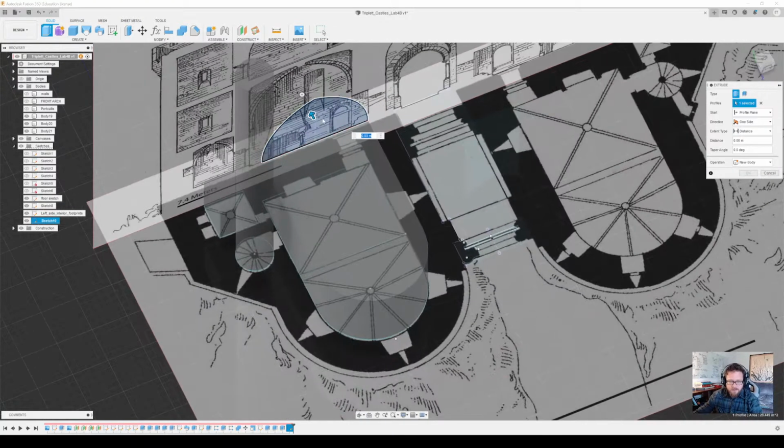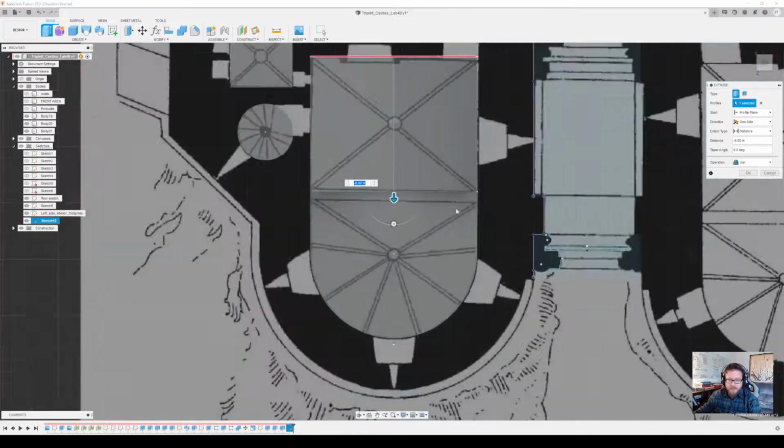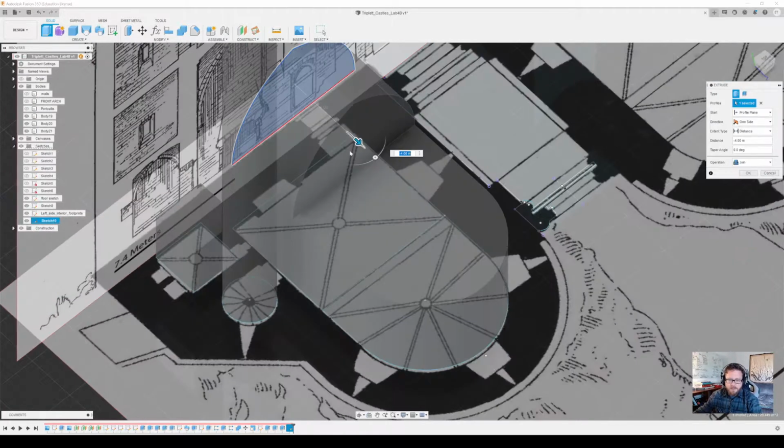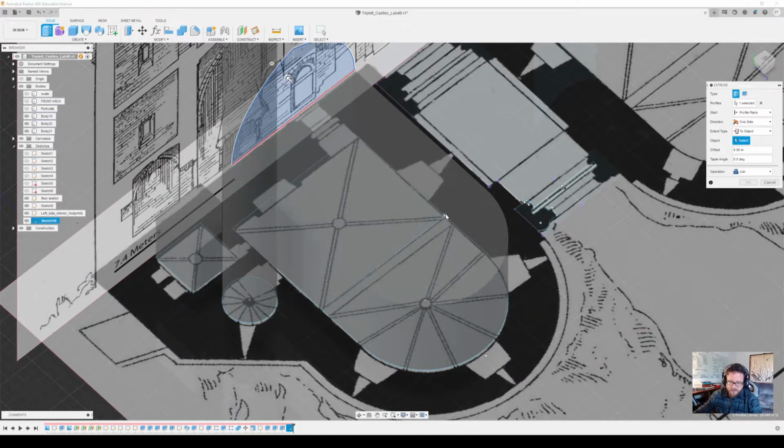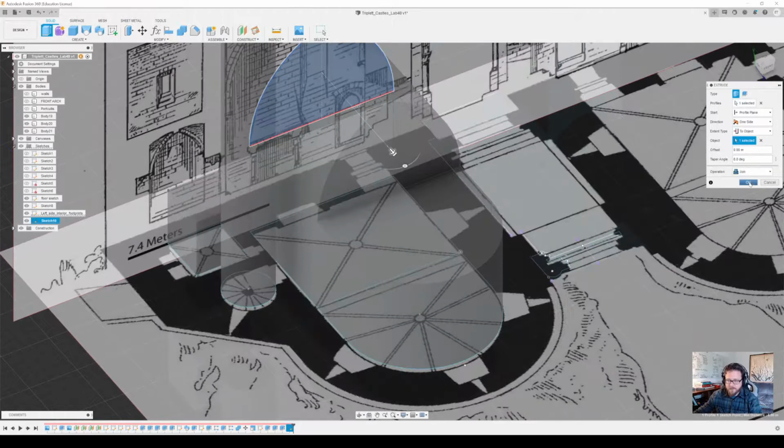Okay, so there's a couple of ways to do this. I can pull it out like this and then look at the top view, and when it lines up with this line, I can say -6, that's fine. Or alternatively, there's another option I haven't shown you all yet, which is you can do your distance right here, and it says you can measure. I apologize. We want to go to, instead of extent type, we want to go to an object. So what I'm going to do is say to object, and then say extrude it till it hits this point here, and that, if you look in the top, is what we're actually trying to snap to. So that's a useful trick.